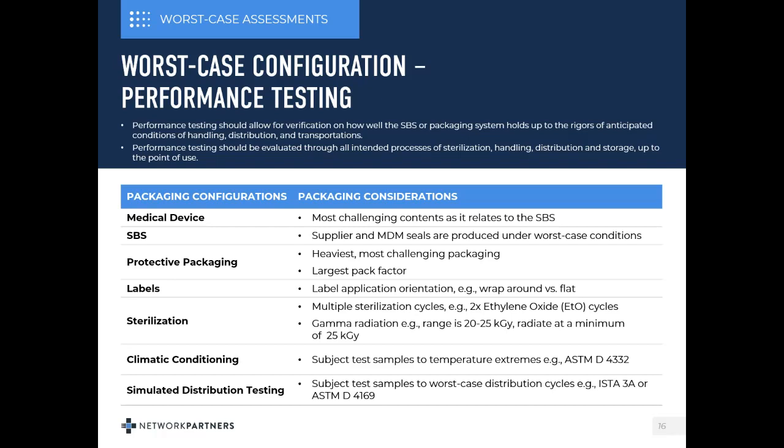And then you go to the sterile barrier system itself, and let's say you do a preformed tray going into a shuttle sealer where you just put the Tyvek lid stock on. You're just going to do a mold qualification on that and probably randomly pick out trays, measure them, and use that for your testing. For the pouch itself, you're going to order them with the supplier, which they're more than happy to do for an extra few dollars.